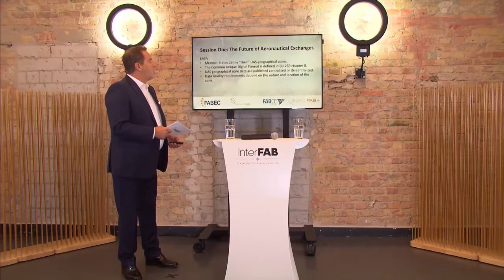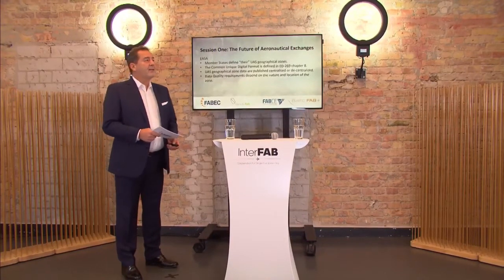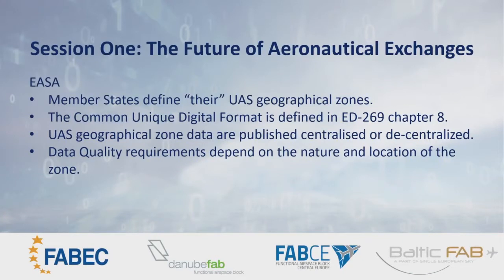A last presentation in the first session was from Thomas Oster from EASA, who was talking about the new EU regulations on drones and specifically about the UAS geozones. That member states have to define their zones themselves, that the common data format is defined in EUROCAE ED-269 Chapter 8, and that the geographical zone data are published centralized or decentralized. It's up to the states to decide. And the data quality requirements depend on the nature and location of the zone.